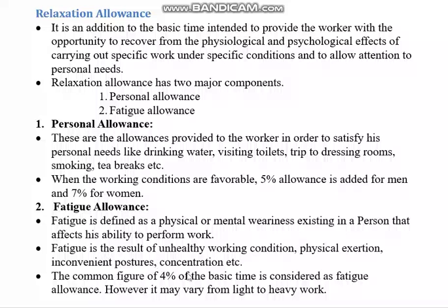And the concentration also. If a deafening noise is there, somebody is drilling a bore just outside your machine shop, shop floor, can you concentrate with the same concentration as when there is not that noise? You cannot. Concentration also matters. Because of all these things, fatigue comes. So because of that, you have to provide fatigue allowance.